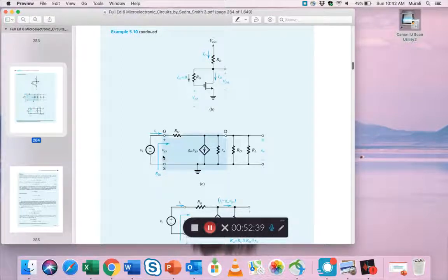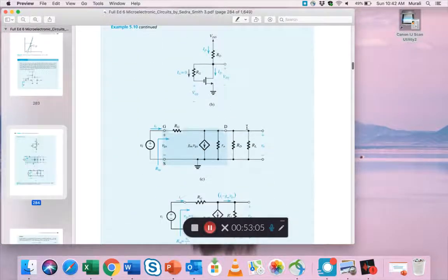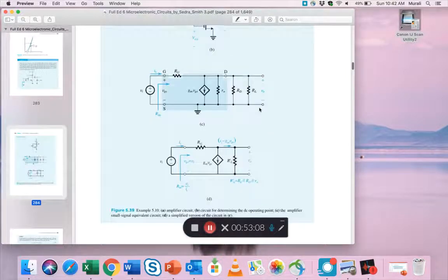Now because there is no other resistance, this almost seems like in series, right? Really it's a parallel resistor, but hey, there's no other resistance, or this resistance is always 0. So we have one resistance on the input side. On the output side, we have two other resistances in parallel. There is the RD, which is drawn like this. There is the RL, which he told us there is an RL, right? This RL. So all this is in parallel. So this makes it a pretty simple circuit. And now we can start simplifying this using standard series parallel methods and so on.